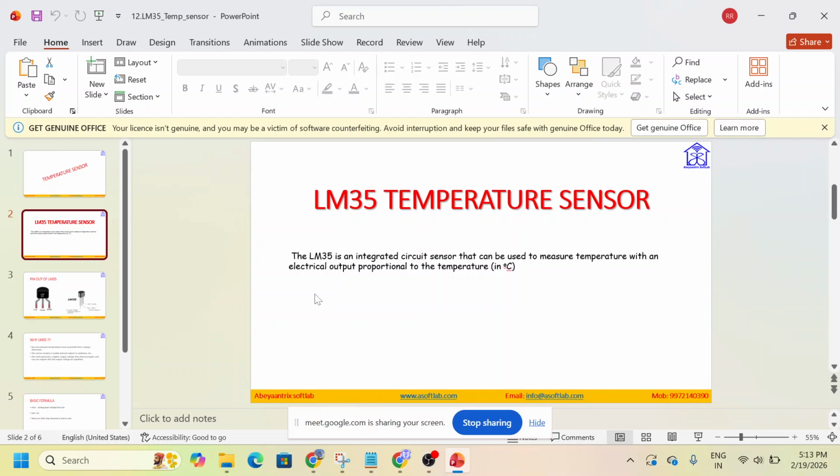Now when the temperature increases, let us take an example of 50 degrees. For 50 degrees the output voltage of the sensor becomes something like 3.53 volts. Based on this output voltage we will calculate the temperature value. Just as when you vary the light on the LDR it changes the analog signals, here when you change the temperature the analog value of the sensor changes.